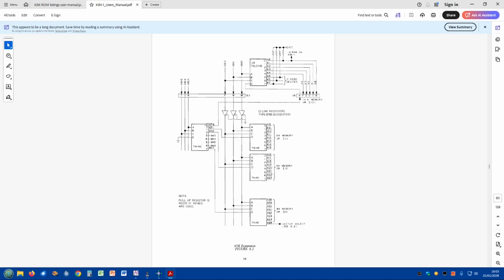You put the bottom one onto there. When these are all 0, this will go to 0, and then you'll be looking at the bottom 8K. This is a full decoding. So then you can have like number 1 here. So if address bit 13 was on and the others are off, this output here will be high and disable that chip, because we want to disable the chip.